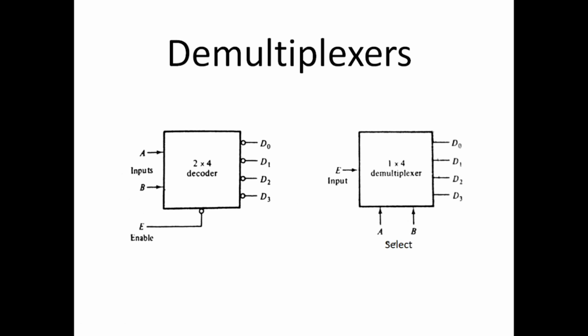So what this demultiplexer does, it gets one single input, and these select lines choose one of the 4 output lines and direct this input to these output lines. So this is a 1 to 4 line demultiplexer. This single bit input is demultiplexed towards any of these 4 lines, and these 4 lines are selected by these two input select lines.